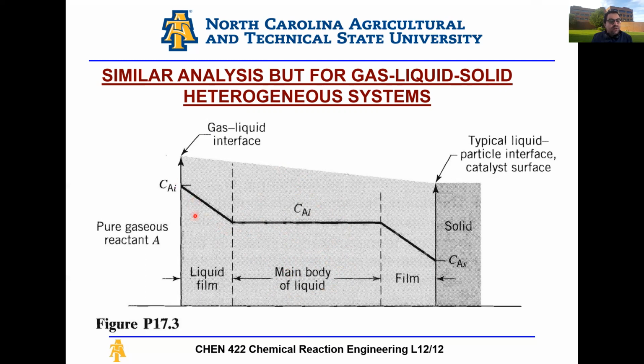If you do it here and you find out that the biggest mass transfer resistance, i.e. the lowest mass transfer coefficient, is at the gas-liquid interface, and this is because we're operating at a very high velocity and I'm only getting very huge bubbles with a very low surface area to volume ratio, so you can design your system now to maybe use a sparger, or a sieve sparger or a perforated plate, which can introduce much smaller bubbles.